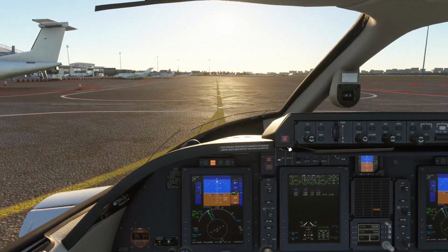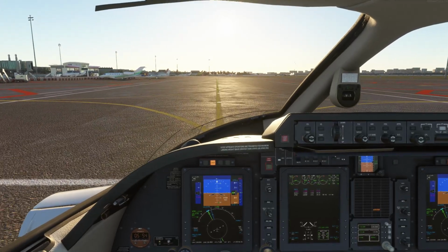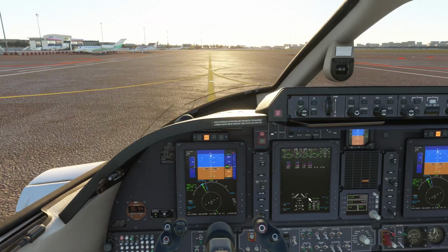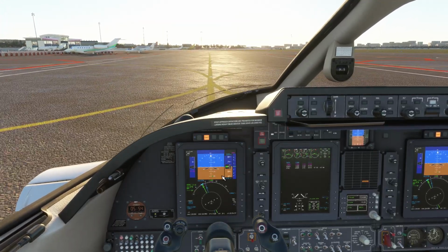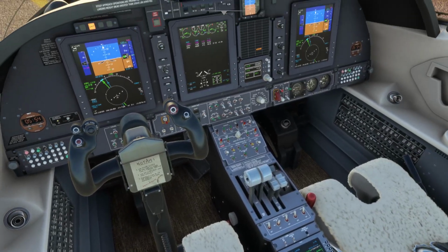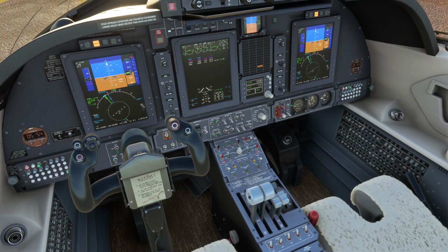Anyway, taxi checklist. Brakes. Let's have a feel. Yep, definitely working. Flaps are mid, synchronous. Steering system is steering taxi. Prop reverse, let's have a look. So I have a key bound to prop reverse. Check.